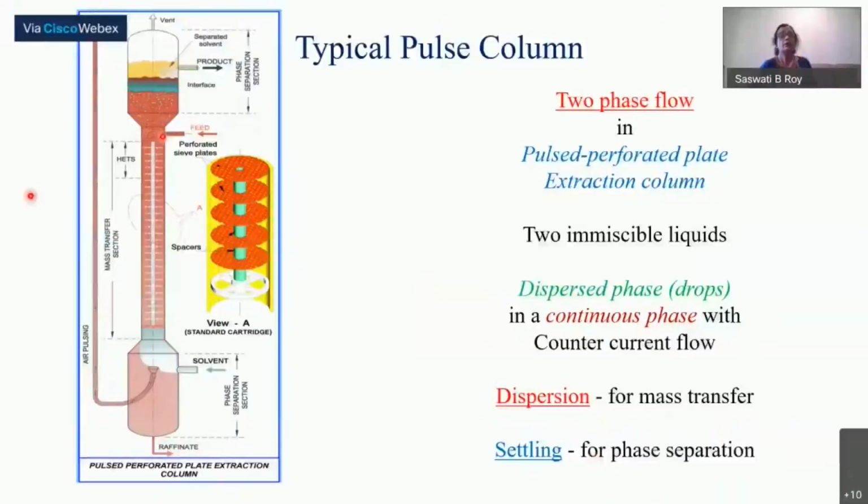This is the column. I said that column is also another equipment where you can do this solvent extraction process. So this is more used for the backend. Actually, in the initial days we started using columns, even for uranium processing also. But due to the inefficiency during size increase due to back mixing, we stopped it, and then we went for mixer settler and slurry extractor. But in the case of pulsed column, size is already limited due to this criticality issue, meaning if you go on increasing the size, it can become nuclear critical.